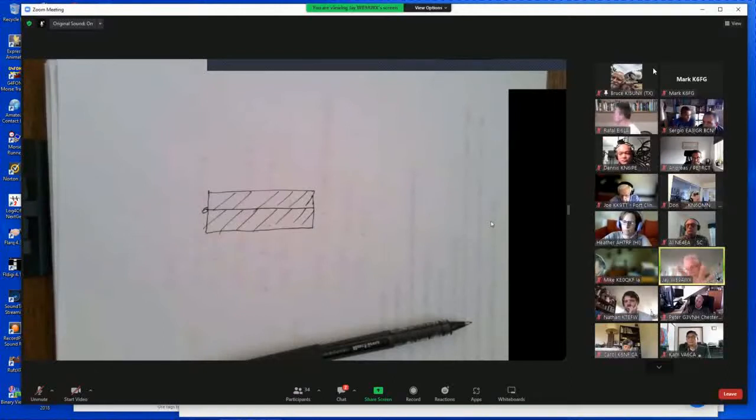That said, you might try putting some kind of filter. There are various ways of doing it. You can get a low pass filter that cuts off at around 30 megahertz. There are also band pass filters you can buy. You can also create a notch filter, which requires a length of coax, and it will basically attenuate that signal.